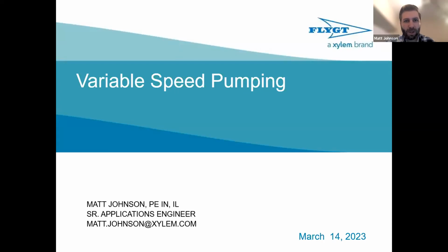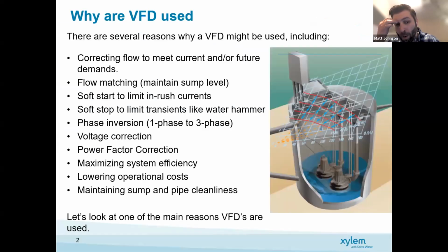Okay, so Sean covered a lot of that information pretty well here. I believe he went through just about all these VFD uses. The one thing I'll maybe add is VFDs can also be used for phase conversion. On most treatment plants you do have three-phase power, but if you have maybe a booster site elsewhere with single phase, you can use a VFD to boost that up to three-phase to run three-phase motors.